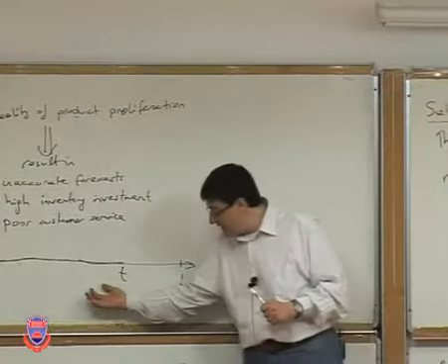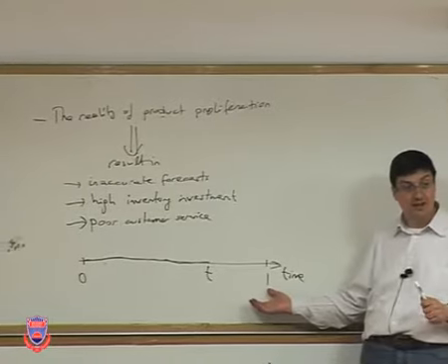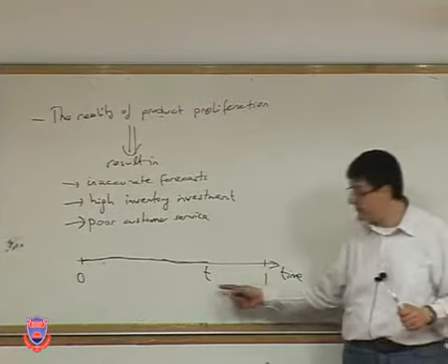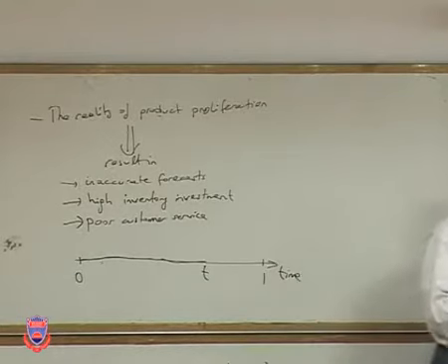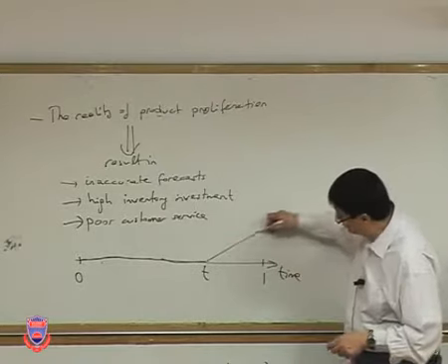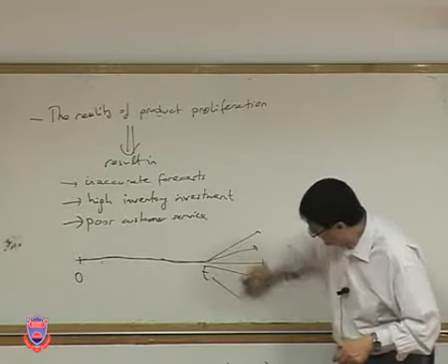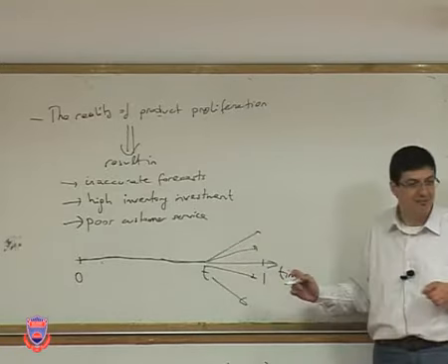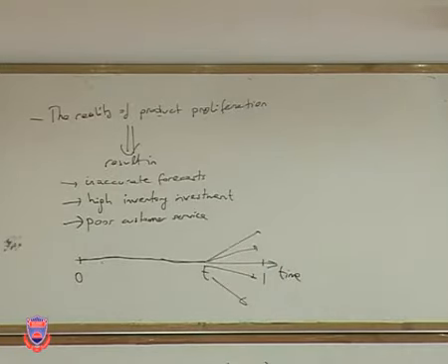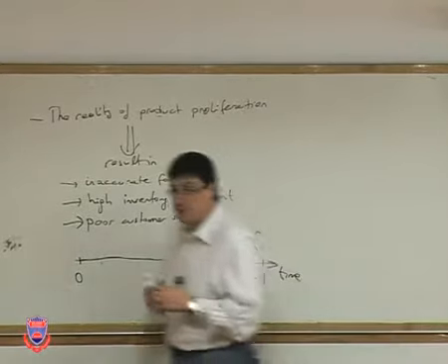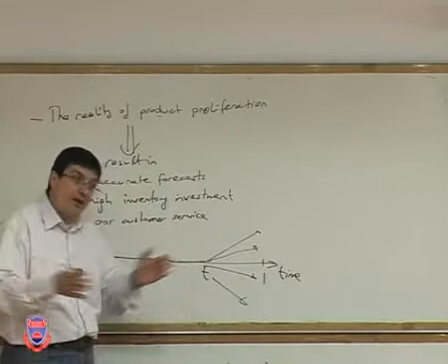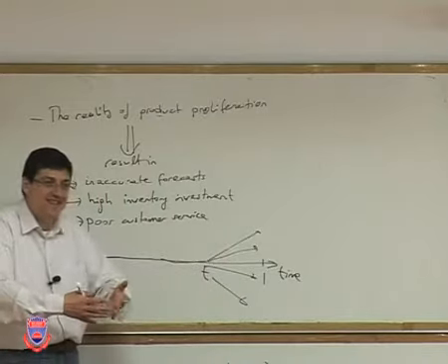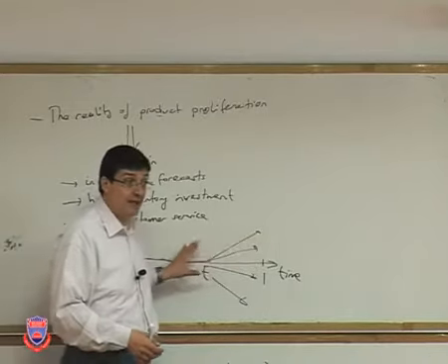Now, the closer we have this t to 1, the more savings we are going to have with respect to work in process inventory, with respect to knowing the demand and manufacturing the individual products accordingly. Because t is now closer to the demand time, the lead time is smaller, so that you can manufacture whatever you need in a better way. And the work in process will be the least possible, because it's going to be common, centralized. Common means centralized, and then you're going to save a lot of money in this manufacturing.